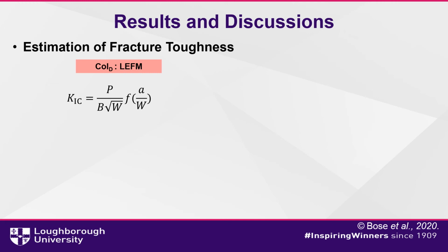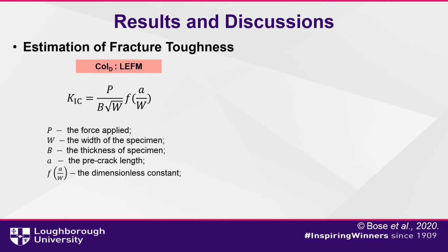K1C can be estimated using the following equation, where P is the force applied, W the width of the specimen, B the thickness of the specimen, a the pre-crack length, and f(a/W) the dimensional constant, which depends on the shape of the specimen.